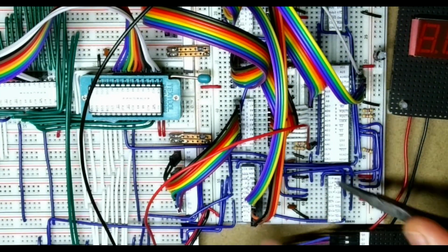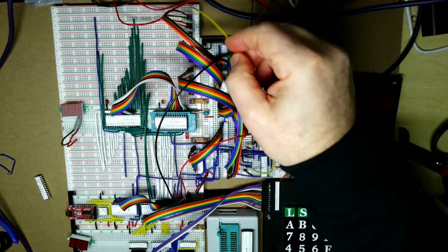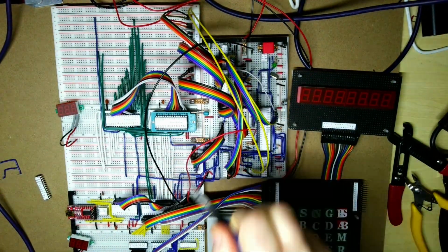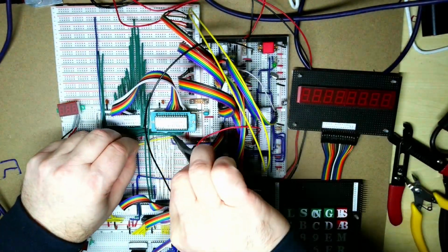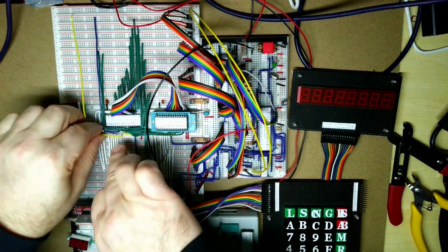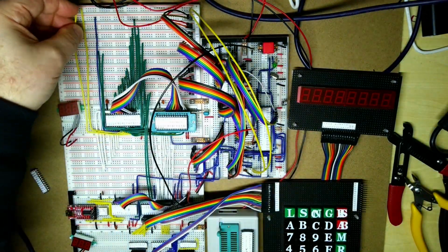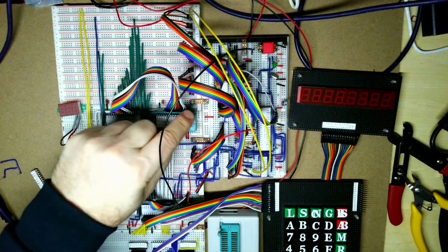And then we're going to have to wire up the memory read, memory write up to the top of the board there. Now we need to unwire the ROM and the RAM from using the lower bus rails up to the new ones at the top there. So that'll be memory read and memory write put in there, put in new ROM.